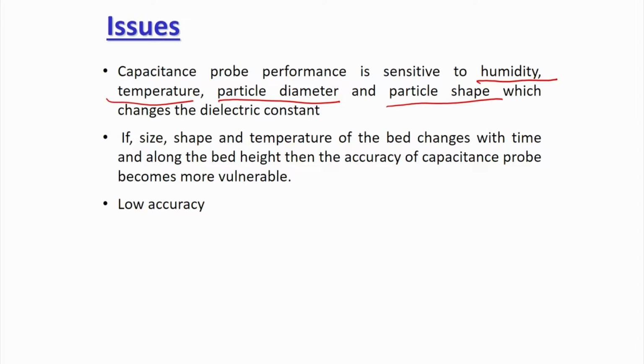That is the major thing, and if the size, shape and temperature of the bed change with time, along the bed height or across the cross section, the use of the capacitance probe will be further limited. In a fluidized bed, there is a chance of some agglomeration or particle attrition.